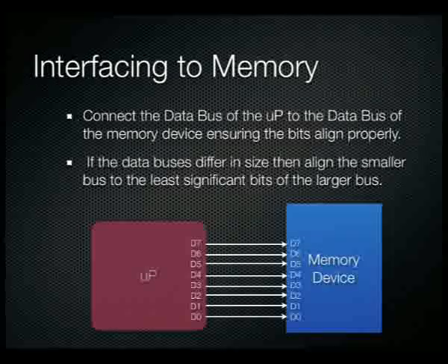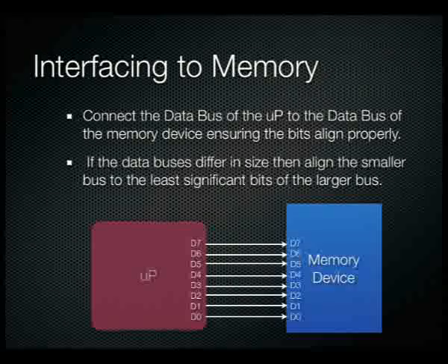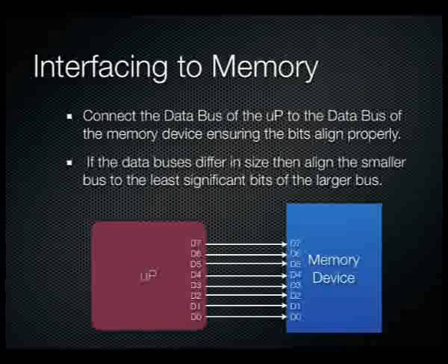Therefore any value you pass from the memory device to the microprocessor maintains the proper magnitude of the number that you're transmitting. If you get the data lines out of alignment, then you're simply pumping through a value that's twice, 4 times or 8 times bigger than what it should be. So you always ensure that you align the data buses to the same pins.